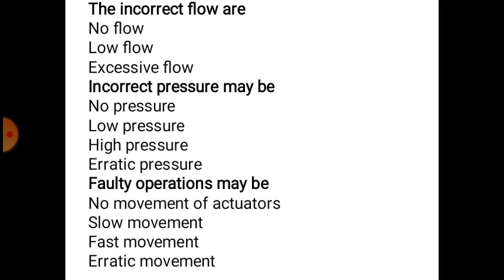What are the remedies for low pressure? Proper adjustment of pressure reducing valve: you must adjust the pressure reducing valve correctly. Cleaning of filters has to be done. Cleaning of reservoir and pipelines. You must prevent the leakages. Replacing the parts and elements: worn out parts have to be replaced. So these are the remedies for low pressure.